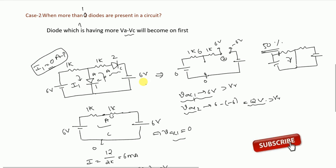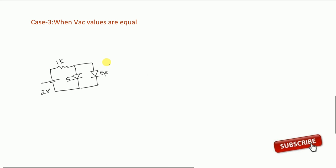And there is another special case in this diode, guys, I will tell you. If you observe this circuit, I have two diodes here. He is asking the current through silicon I1 and current through germanium diode I2. So what is the first step? I should open circuit the two diodes. So this is 2 volt. This is 1 kilo ohm.